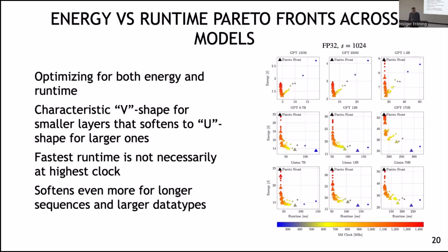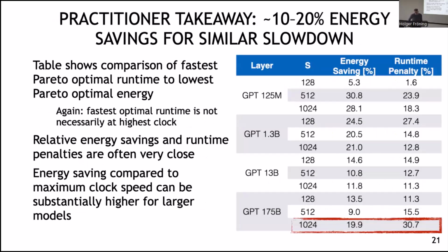And this is for me super exciting research. Yes, we can simply play with DVFS, which is a very easy knob available for us to play with energy optimality, or better said, minimal energy to completion. In summary, we found settings where you can make different trades. But in principle, the common pattern is that you can save up to 20% of energy, sometimes 30%, at the cost of a runtime increase.